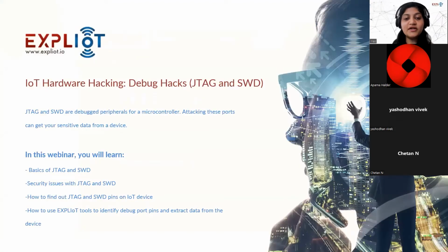Today's webinar is on debug hacks, JTAG and SWD. JTAG and SWD are debug peripherals for microcontrollers. Attacking these ports can get sensitive data from a device. In this webinar, you will learn the basics of JTAG and SWD, security issues with JTAG and SWD, finding JTAG and SWD pins on an IoT device, and how to use EXPLIoT tools to identify debug port pins and extract data from the device.